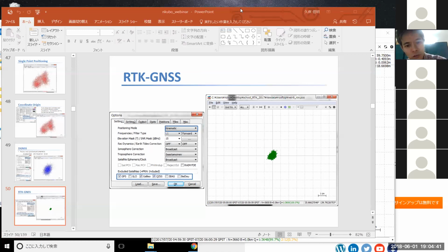As I already introduced, we may have to set up an NTRIP server, and once you set up an NTRIP server, you can use anything. But can we set that NTRIP server inside the base station? So this is the question. Can we use a base receiver as an NTRIP server? The answer is yes with the NetR9.